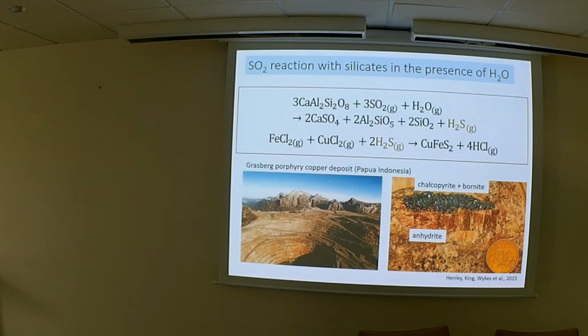You get sulfate, and it's actually a neat way to measure grain sizes and grain morphologies in the marble, because when we did the X-ray tomography, the interfaces of the grains light up really nicely because they have the sulfur in them. That's how they measured the grain sizes of the marble, which wasn't possible with XCT before because everything is the same density. Then we put it back in the CO2 furnace, moved back to sulfate, moved back to calcite. We did that 2 or 3 times, and the texture remains the same, but it's just replacing one with the other.